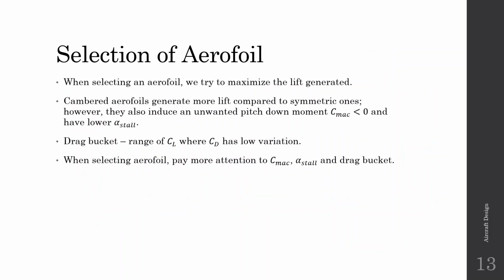One more thing that sir discussed was the selection of airfoil. When we select an airfoil, we usually try to maximize the lift generated, so that with a smaller wing we can lift the whole aircraft. It has been seen that cambered airfoils generate more lift compared to symmetric ones.